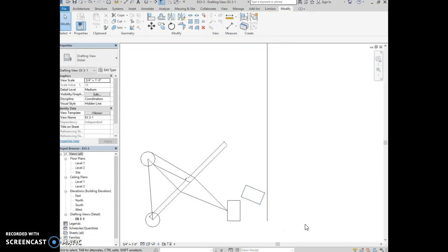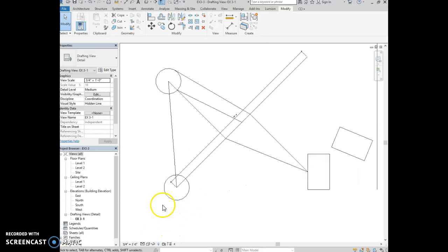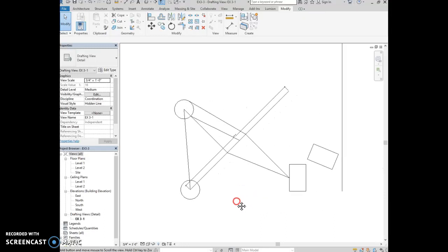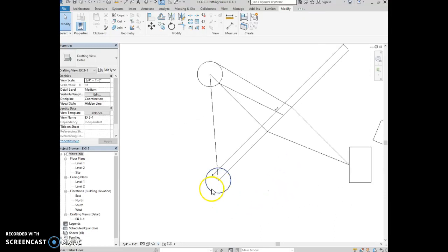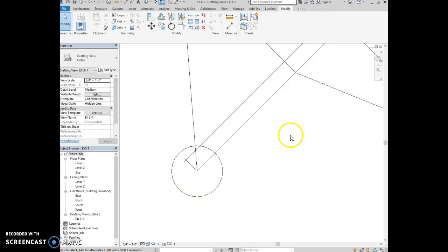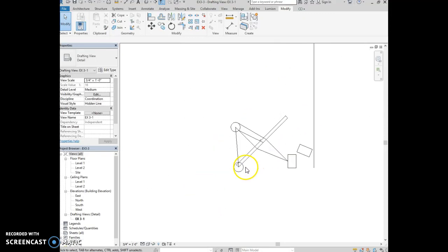The scale tool. So the scale tool has similar steps to the rotate tool. First, you select what you want to scale or resize, specify a scale factor, and then you pick the base point. The scale factor can be provided by picks on the screen or entering a numerical scale factor. Let's try to use the scale tool to adjust the size of this circle near the bottom of the page, so this circle. I'm going to zoom in on this. So if you want to pan, if you hold down your mouse wheel, you can pan across the drawing, and then you can use the mouse wheel to zoom in on an area that you're working on. And I suggest doing this because sometimes it's hard to see things when they're so zoomed out.